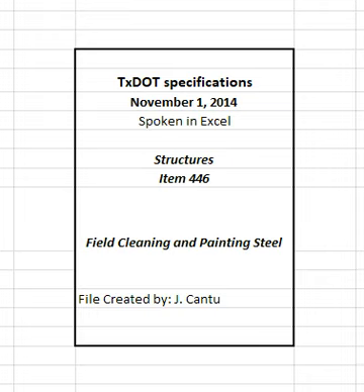Remove tree limbs, bushes, grass, and other items that will interfere with the cleaning and painting operations as directed. Remove vertical clearance signs, and erect and maintain temporary ground-mounted signs matching the content and letter size on the existing sign unless otherwise directed. Reattach permanent clearance signs as directed.